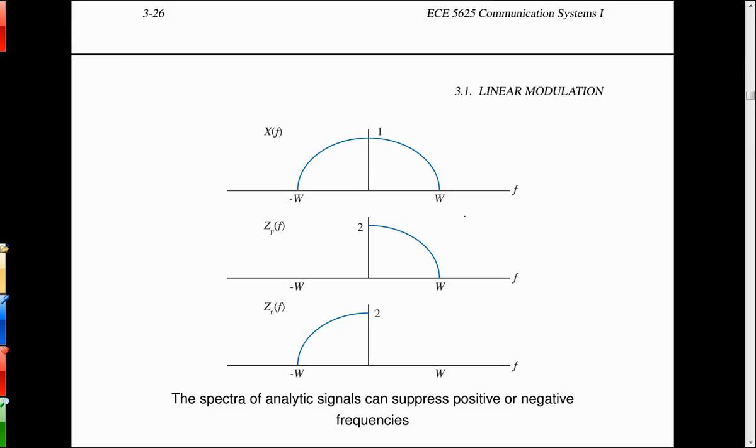What you can do is bring in a real signal from a single A to D, and then you can get access to the signal and the analytic signal by post-processing with a Hilbert transforming filter and then a straight-through path. And what it allows from an architecture standpoint is you can get by with only one A to D as opposed to two. It's just a technique that allows you to do processing at the front end with less hardware or matched hardware.